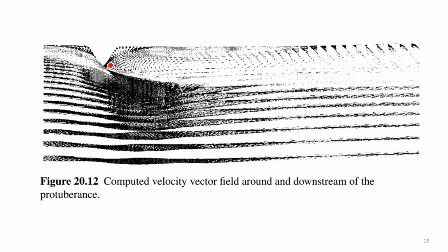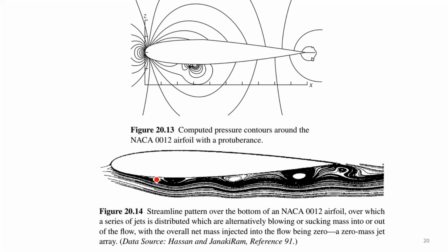that there is a vortex behind the protuberance here, a vortex which is destroying the flow, and the flow is going around not just the protuberance but also around the vortex itself. So the amount of recirculated flow is big, and it increases along the length of the airfoil.